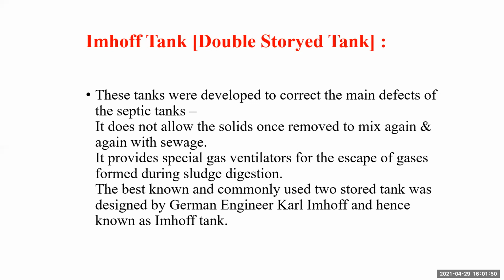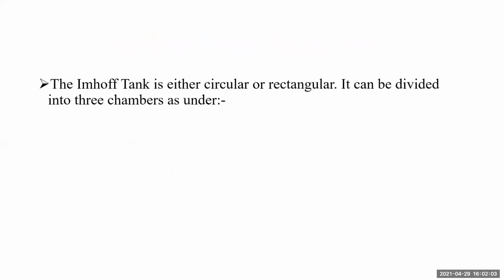The best known and commonly used two-storied tank was designed by the German engineer Karl Imhoff, and hence the tank is known as Imhoff tank. It is actually a double-storied tank. Imhoff tank is either circular or rectangular. It is divided into three chambers.